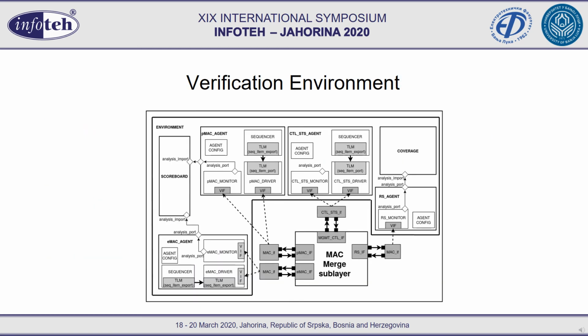This is our verification environment according to UVM methodology. There is, of course, the MAC merge sublayer as the device under test or DUT, and many other components to support this test. So we have components such as monitor and driver that enable sending stimulus to the DUT and also collecting responses from the DUT.